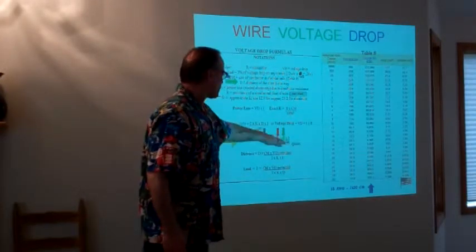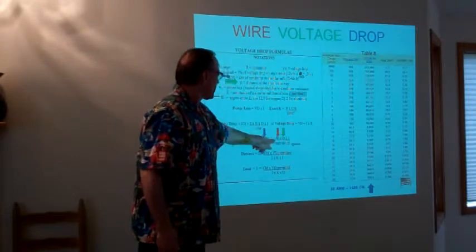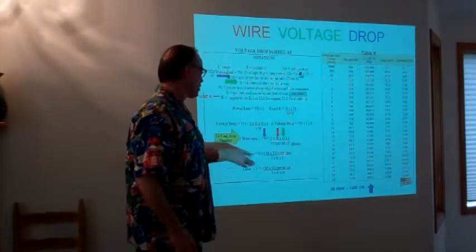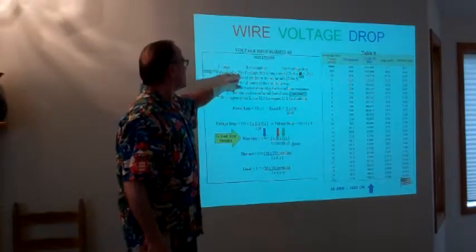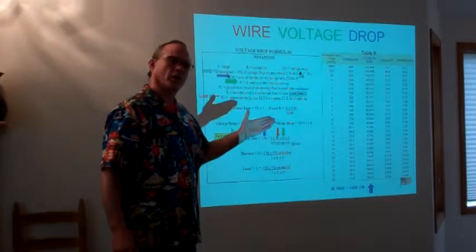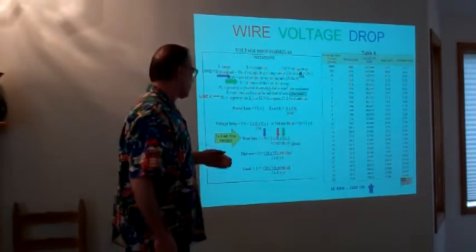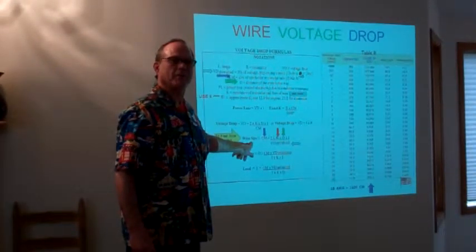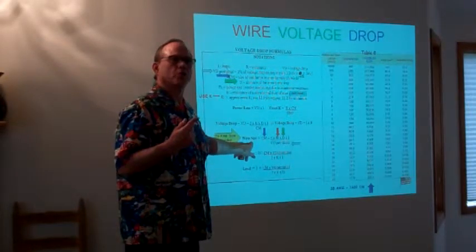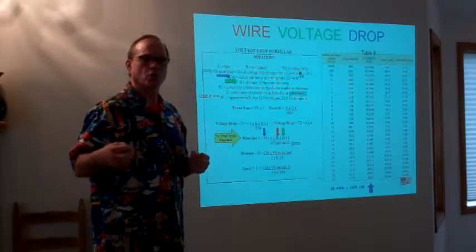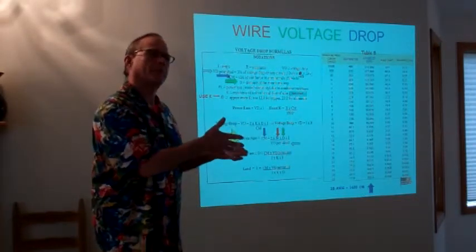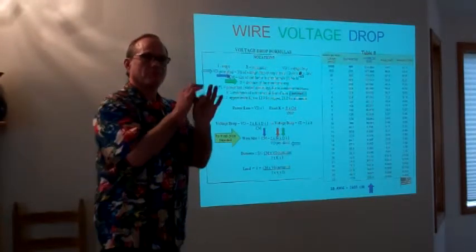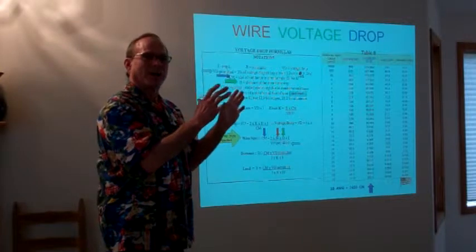So with those elements, we basically multiply those together and divide by the voltage drop permitted. All you have to remember about VD is that it's 3% of whatever voltage level, whether it's 12 or 5 volts, doesn't really matter. Still the same thing. And the reason we want this is so we can size our wire for that voltage drop. Now keep in mind one thing. What we're doing here by sizing our wire is keeping our wire cool. Just like we were using 80% of our power supply, we're now going to size our wire so that it is cool as well. Just making something larger is not going to affect my voltage.